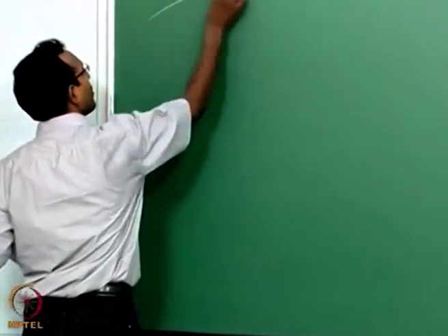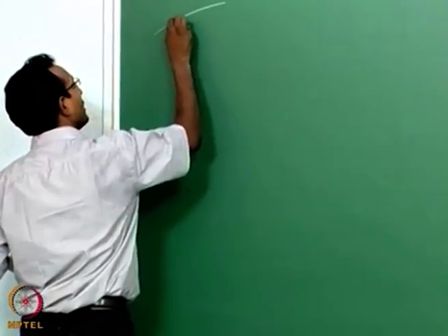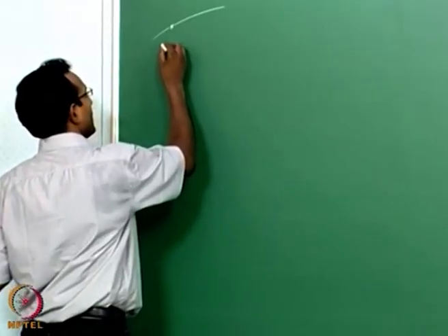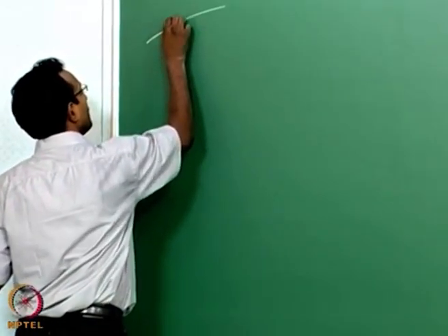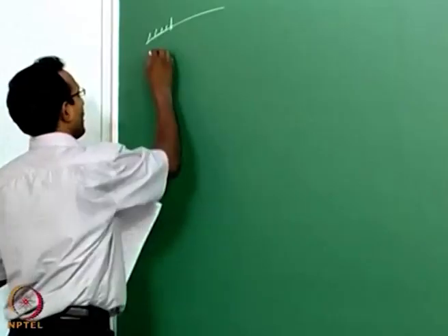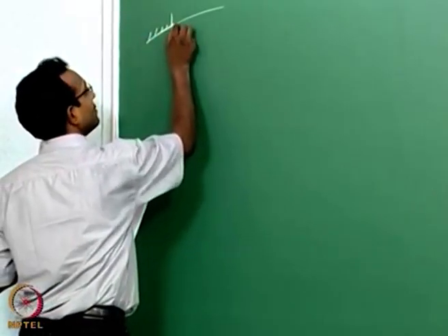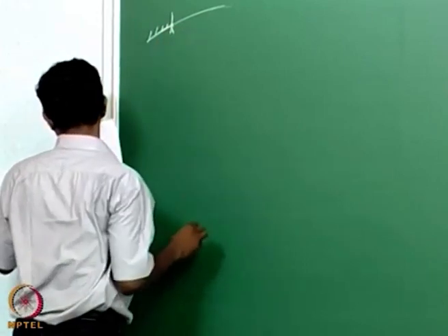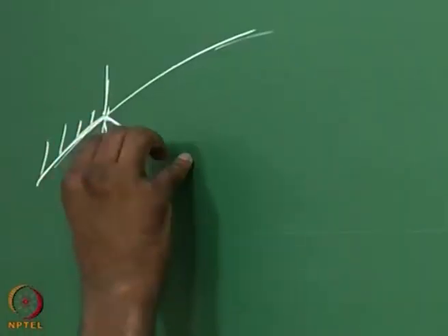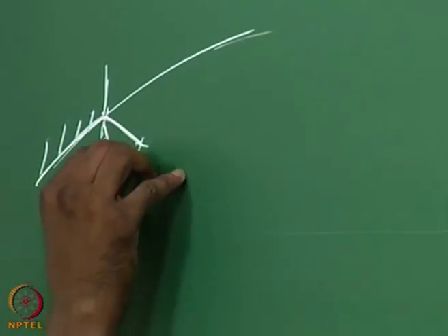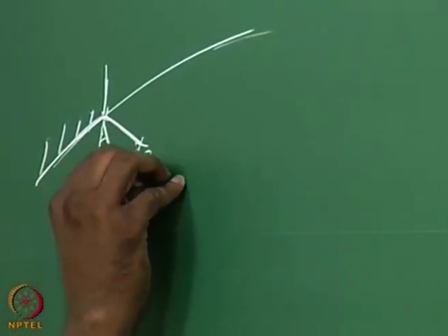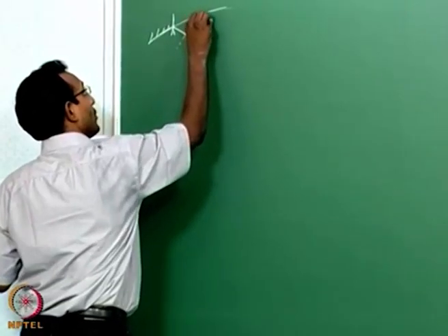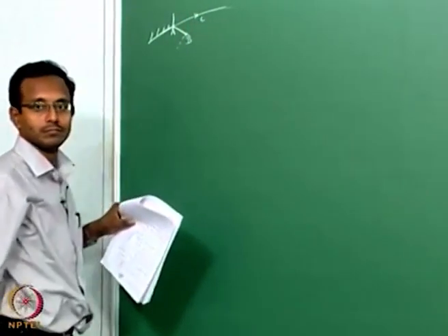Say I somehow know an already existing point on a boundary. This is my nozzle wall, and I know how to solve this, and suddenly there is a free jet going outside. Say I know this point A, and I have already calculated, on this side, the interior point B, and now I want to find a point C. That is my goal.